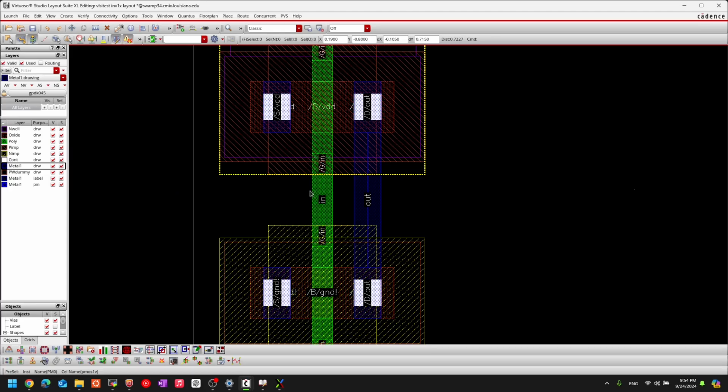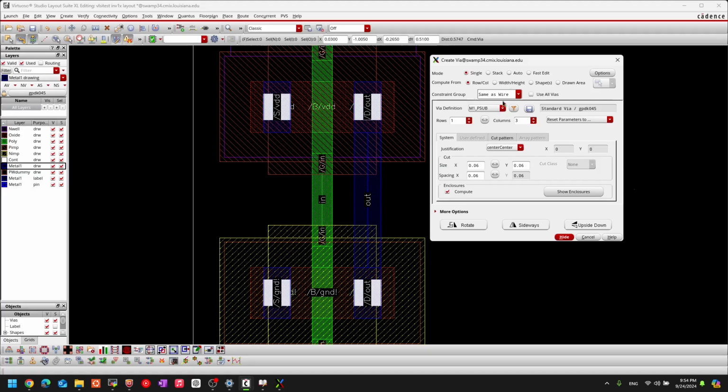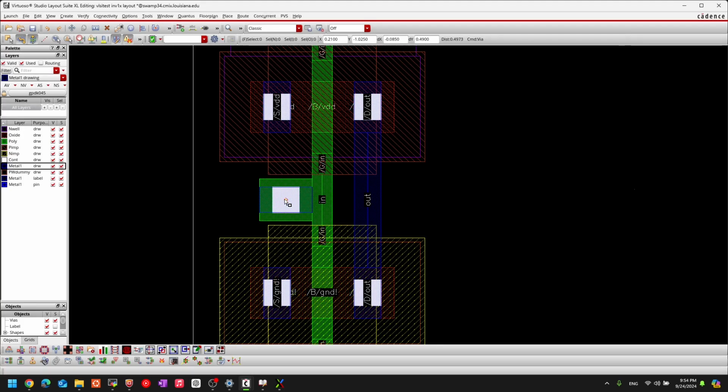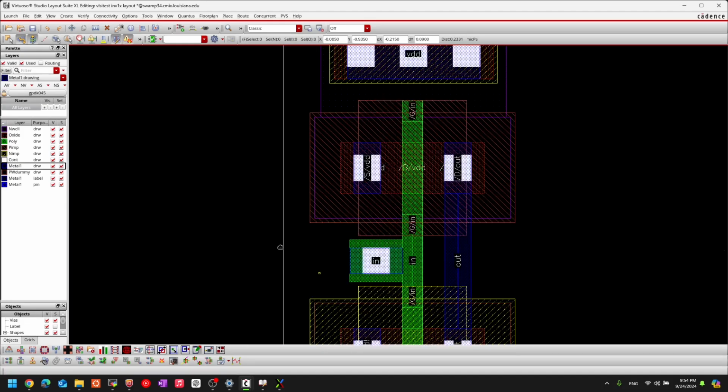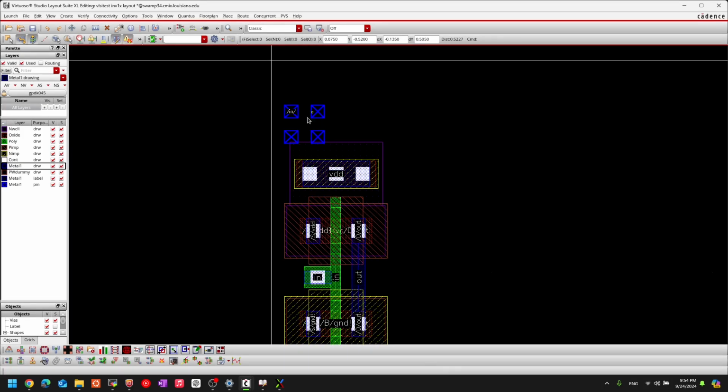poly. So in order to do this, again, press on O, and then from O, here we have to look for metal 1 PO. So metal 1 poly. Select this, and you got metal 1 poly. So be sure to rotate this, just so it aligns with the metals that are coming in. So we got this connected. Now, I am currently violating something here, but I won't tell you right away because I want to show it to you in the DRC violation window.